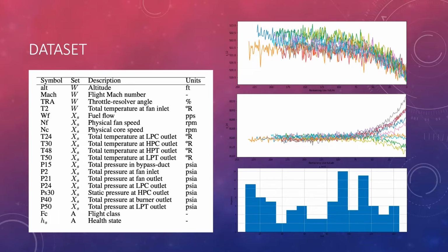So we are considering a window of this particular data at a particular time, and then we are trying to find the RUL. So as I told you, the remaining useful life right now, maybe if it is 24, after maybe a couple of flights it will definitely come to 22. If your model is good and your inference was actually good, definitely it will be going down. So what you will see is that the remaining useful life is a decreasing number, and the Y is nothing but your target value that you try to predict.